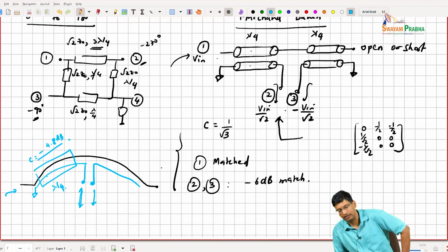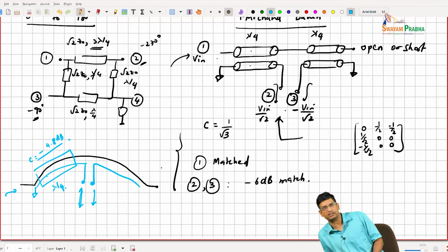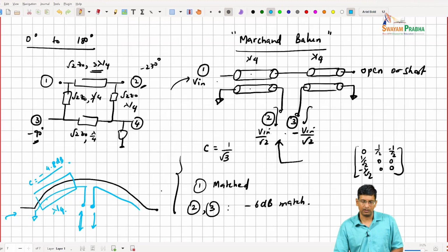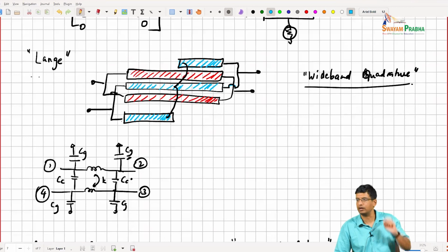So this balun from an integrated perspective works very well. Again, you can see that it looks a lot like coupled lines, which it is, right? One of the notes is that when we are trying to do even mode and odd mode impedances, we basically assume the same L in even mode and odd mode.